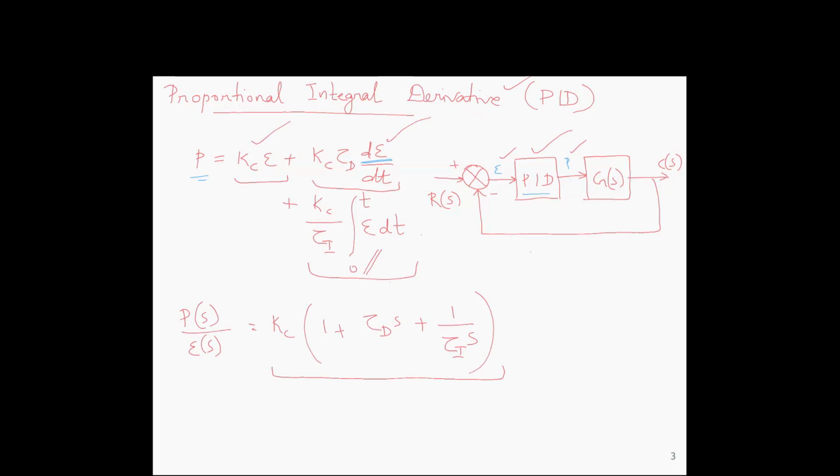Now we will see a few points which will be helpful in deciding which controller is to be chosen in which situation. Suppose you have some noisy error signal. If we are using derivative control, we are taking the derivative of the error.